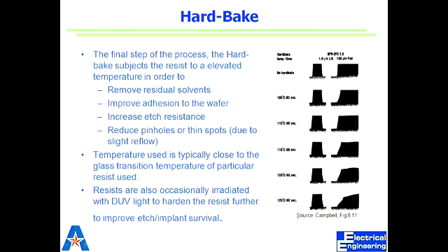So, there are different pinholes, and different materials would require different techniques. How do we figure out the defect of pinholes? For resist, there is obviously no way to find pinholes. It would come out only as a defect once we are done with the treatment, whatever we are supposed to do. In etching, it will come out as a small pit in the substrate.